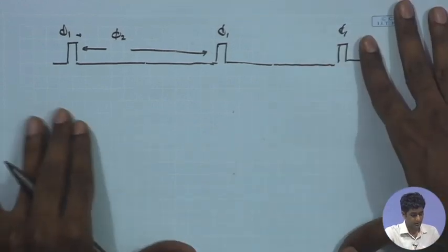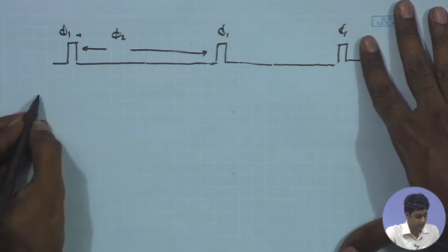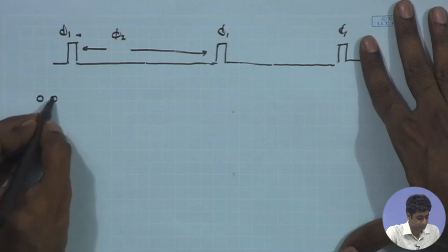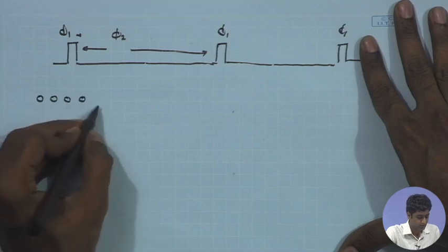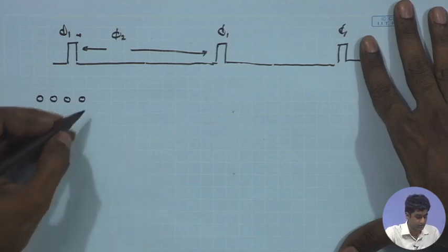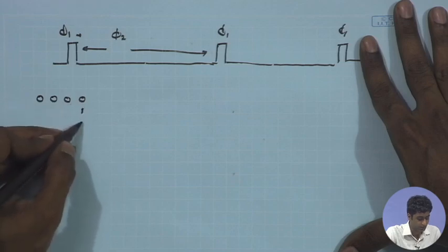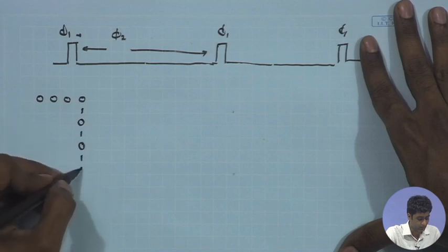So, if we look at the overall operation of counting, ultimately we have say 7 bits. Suppose I am just looking at the last 4 bits, and the overall operation that each of these bits performs. You have the LSB, the least significant bit, starting from 0, it goes to 1, 0, 1, 0. So, it alternates every clock cycle.